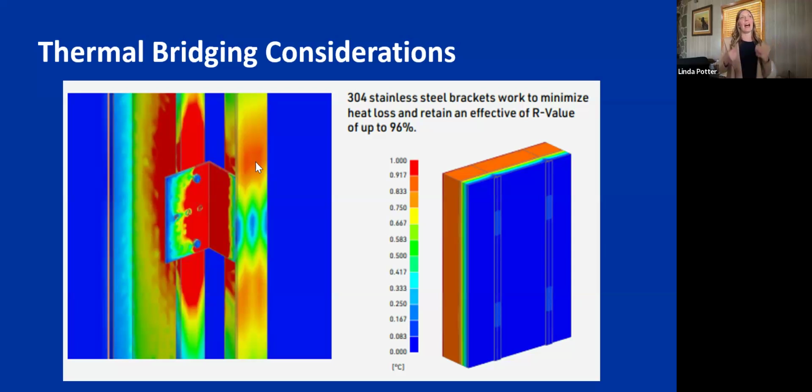So I think we have this perception, and depending on what project you're designing and your owner requirements, you might need a true thermal break in order to get the U value or R value you're looking to meet your energy codes. But this study and the values that we got back indicate that you don't necessarily have to, because a stainless steel connection is actually pretty thermal efficient.